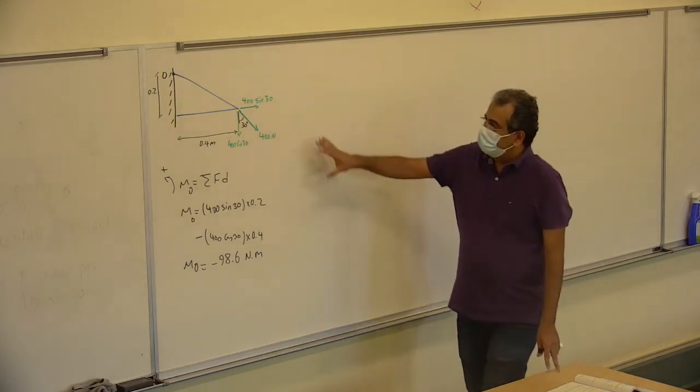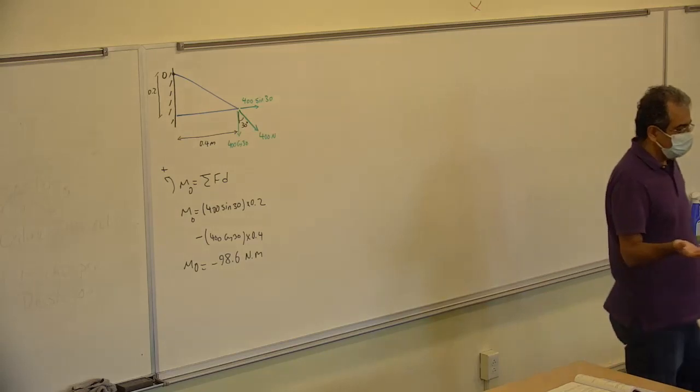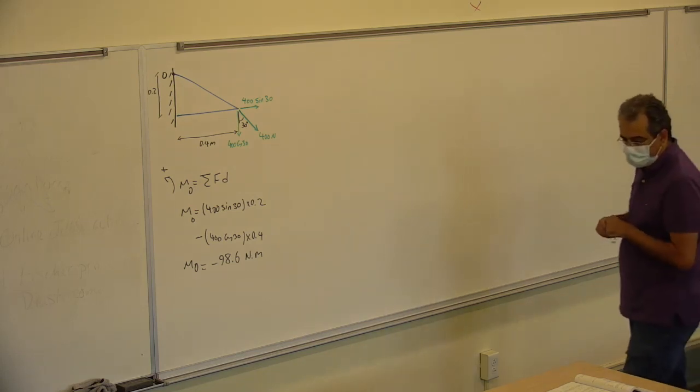So again, just remember, if you want to calculate the moment about any point, it's much easier to find the components on the x and y axis, and then go ahead and find the moment for that point.